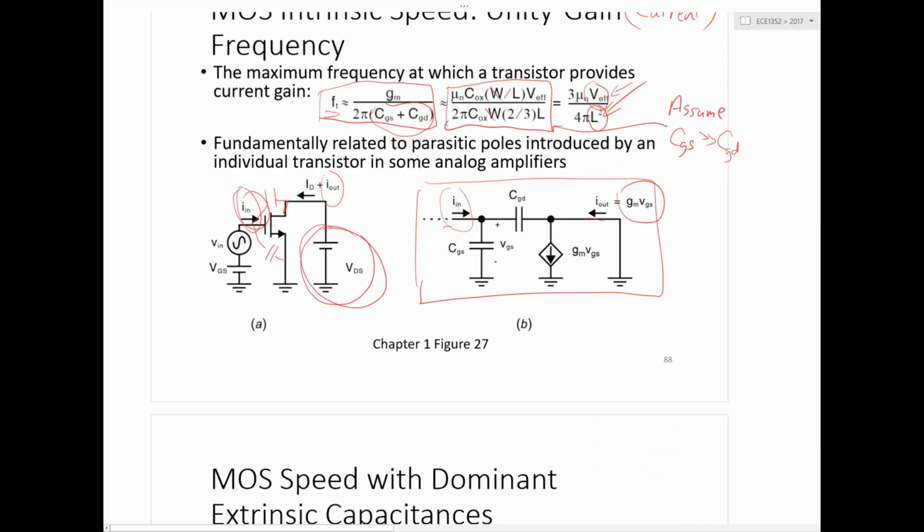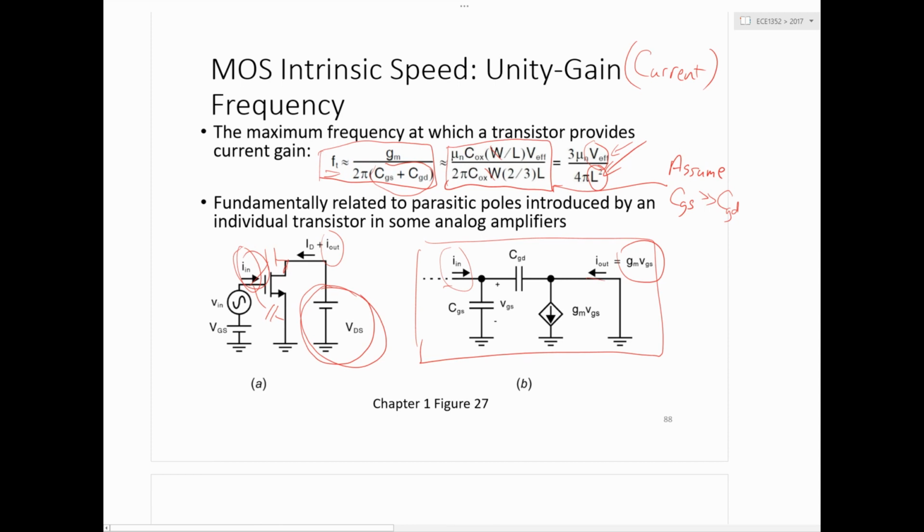The only case where you would bias with a high V effective is where there are no other significant load parasitics connected to the transistor. In that case the intuition is pretty simple too: sure, then you want to make the transistor tiny if what you care about is speed.